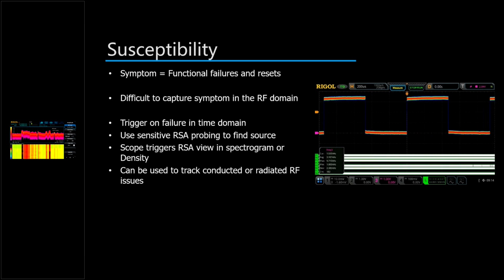So instead of that smooth frequency cycle like we were seeing when we were looking at it in the last video, what we're seeing here is this sort of occasional clipping reset function. And so this is really a functional failure reset of our board that's causing us problems down the line in our embedded work. And so, how do we find the root cause on this embedded problem? Well, we can capture it.